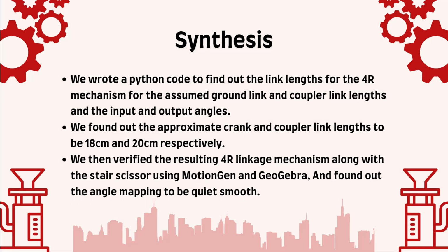Thanks, Dhruv. Once the dimensions were set, we moved to the synthesis phase. We didn't just guess the linkage movement, we used a 4R linkage mechanism to guide the scissor lift. We wrote a Python script to calculate the exact link lengths required for the input and output angles. Let me show it to you.